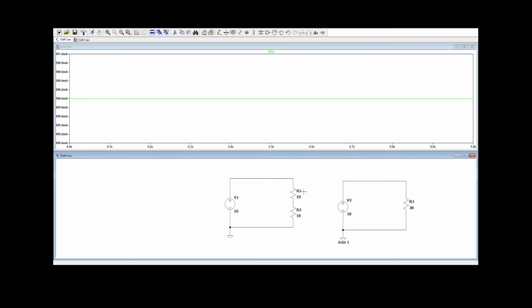So in tackling a two resistor problem, what you can do is add the two together. Now you can use Ohm's law. The trick behind Ohm's law is it only works on the voltage across that particular component.